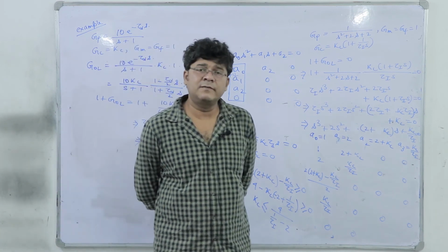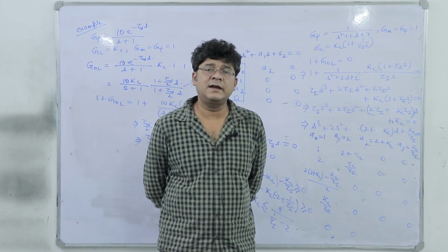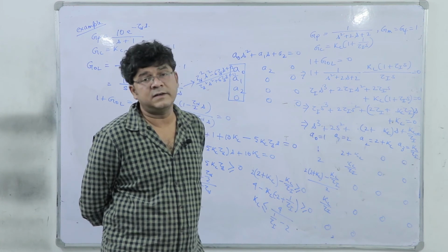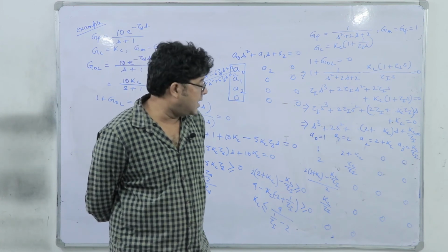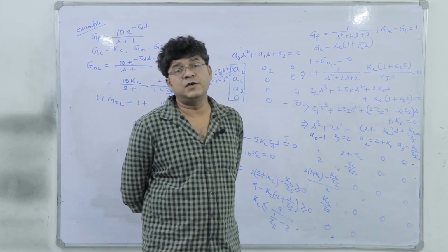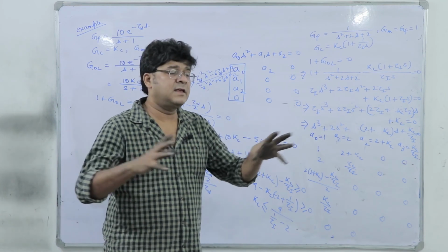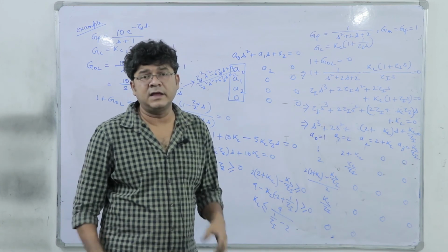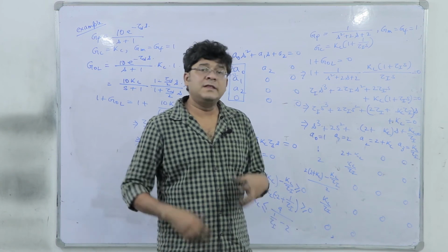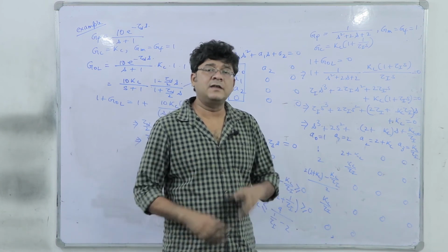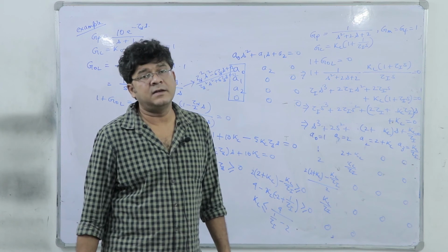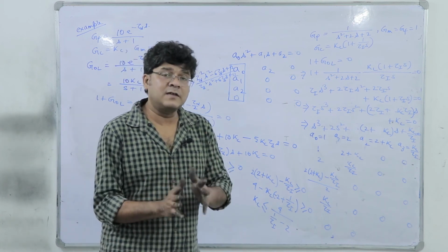That is the domain of tuning, and there are different tuning techniques, criteria based on which we can exactly fix the values of this controller parameter like kc, tau I or maybe tau d. But here, whenever you are designing a controller, it's very, very important that you must first ensure the stability. Right. Even if you think that you have applied some empirical tuning technique which does not consider the stability criteria as its baseline condition, in that case, even if you get a good controller design and it can control the process, for some input the output blows to infinity and the output becomes unstable. So that must be taken care of.